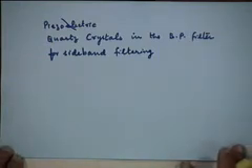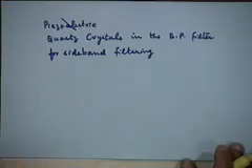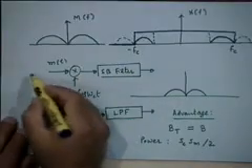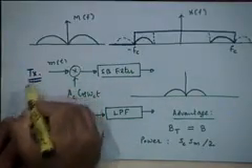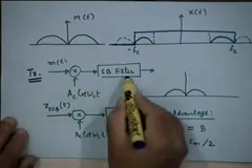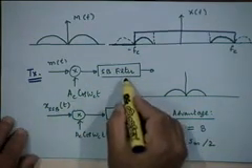Yes, please. You said that using single sideband modulation we can actually reduce the bandwidth from 2B to B. But the thing is we are still transmitting in that region. We are just removing it at the receiver via a filter. No, no. This sideband filter is at the transmitter. This is the transmitter. We are putting the sideband filter before transmission.